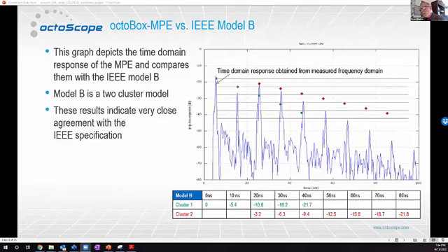So the delay through a Butler matrix will probably look more like just one impulse. Whereas in a multipath, meaning there are multiple different time delays as you go through it, it will have multiple impulses showing the delayed copies of the signal. I think also when we get to the response, we'll see the multipath in frequency. So we should just keep going.